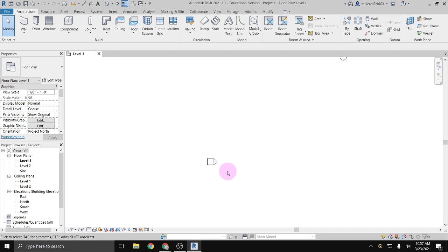So you can remember from our practice, we would say, oh, this is view 1 on sheet A202. It'll automatically fill that in once I define my sheet names and start placing views onto the sheets of paper. All of that will get filled in, which once again just makes it so much easier to sync all your drawings and make sure everything's working the way you need it to. But since these are my elevation view markers, I just want to make sure that whatever I'm drawing is inside these 4 views. We of course can move them around if we need to.